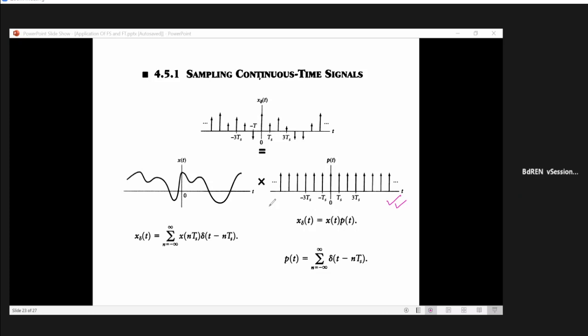By putting a switch there, for example, say your signal is s(t). We have a switch turning on and off. When the switch is on, you will get output. When the switch is off, we will not get output. This type of sampling is used in practice. We have zero order hold and first order hold type circuits there.